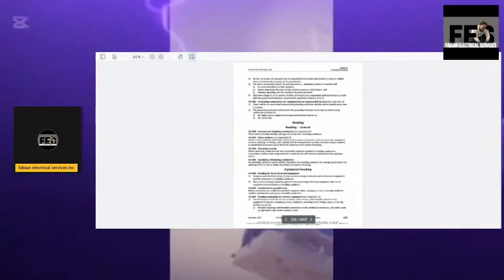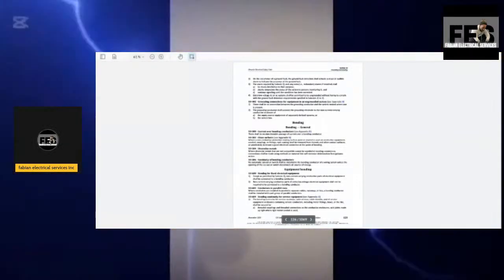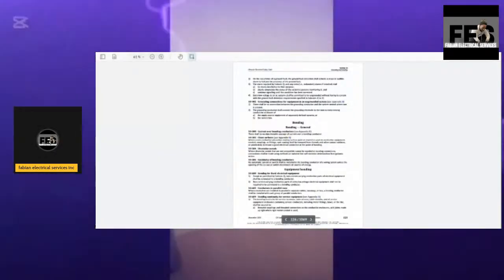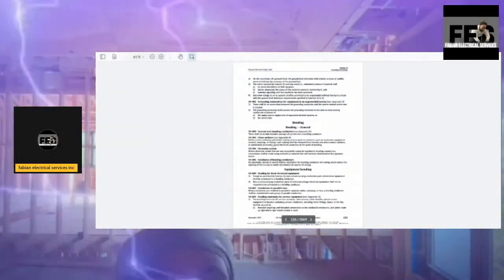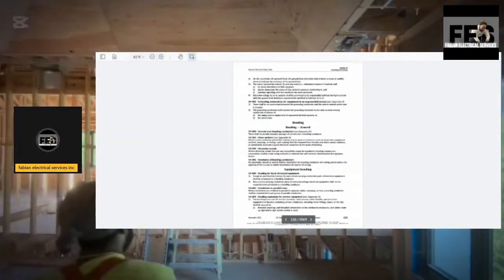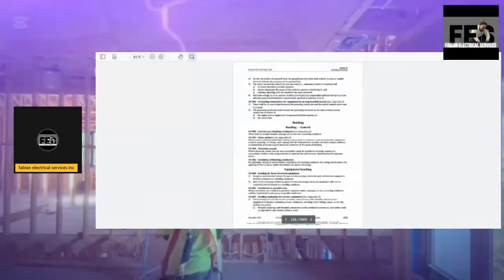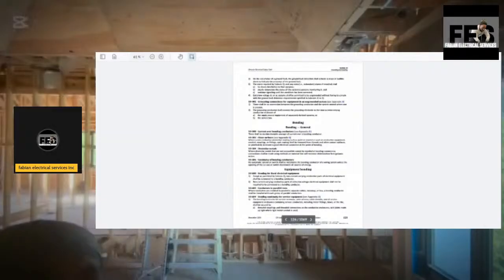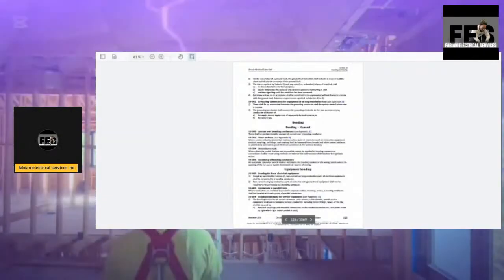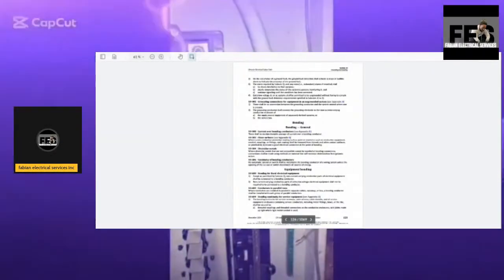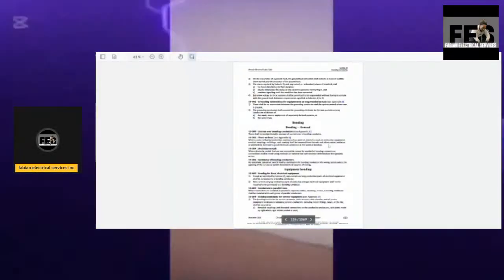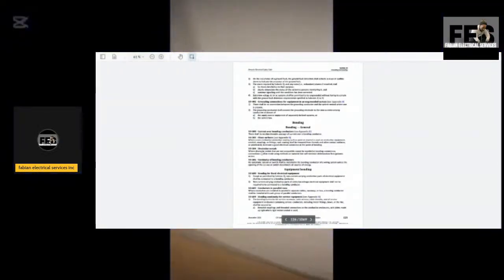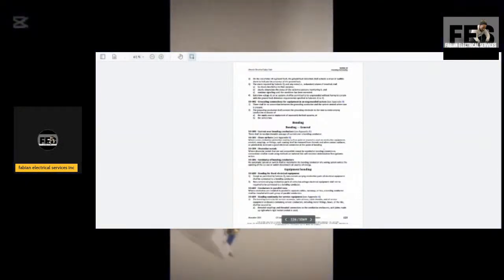10-500 Current over bonding conductors. See Appendix B. There shall be no objectionable passage of current over a bonding conductor. Clean surface: where a non-conductive protective coating such as paint or enamel prevents its use on conductive equipment, conduit couplings or fittings, such coating shall be removed from the threads and other contact surfaces, or penetrated, to ensure a good electrical connection at the point of bonding.